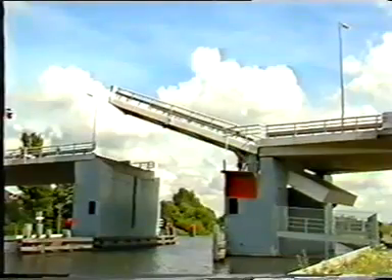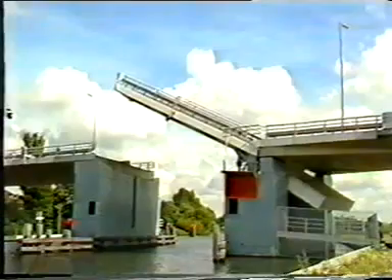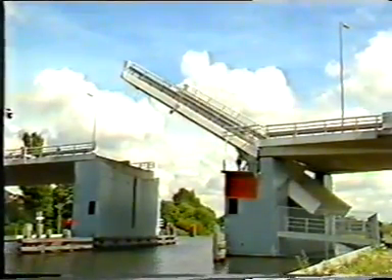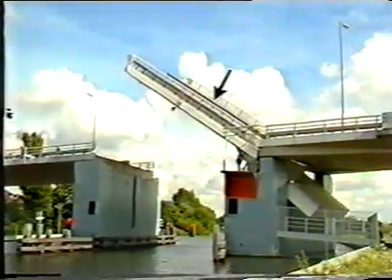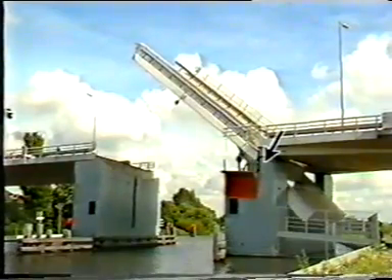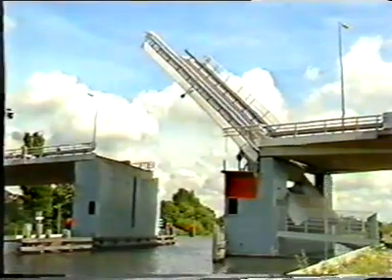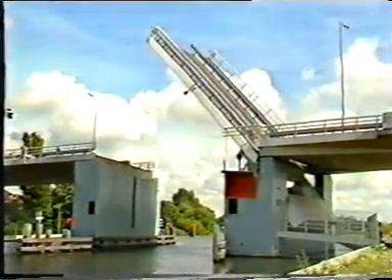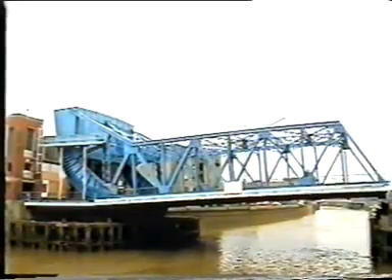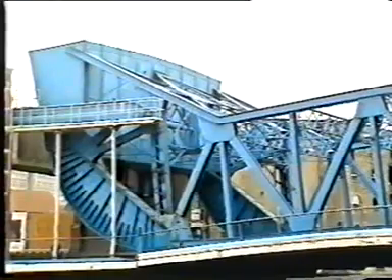The bridge rotates with respect to a fixed point of rotation which coincides with the center of gravity. For dead load, the bridge should be in equilibrium in every position. Therefore, the center of gravity of the steel structure, the point of rotation, and the point of action of the counterweight must be located in one line. Also, in a Scherzer bascule bridge, the center of rotation coincides with the center of gravity.